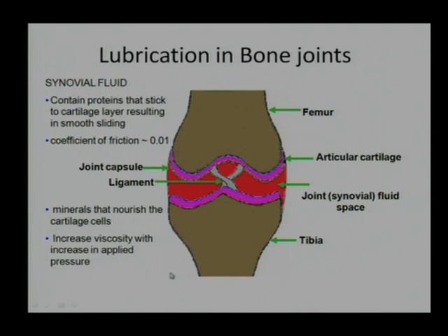Finally, it needs to have a substantial pressure viscosity coefficient. What we are saying is that when the pressure is increased, this liquid should get compressed. If the liquid is getting compressed, it can sustain more and more stresses, or its viscosity will increase, and if viscosity increases, load carrying capacity will increase.